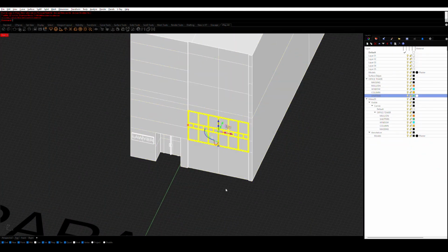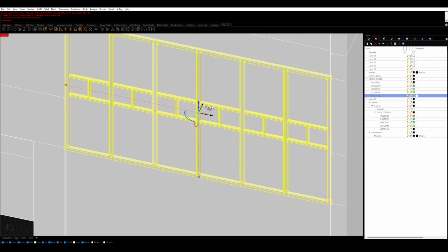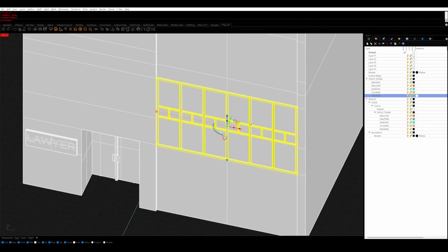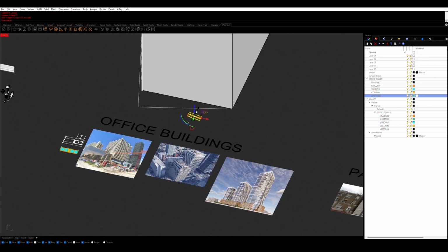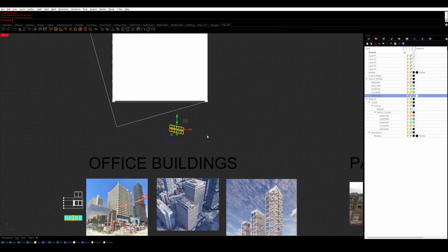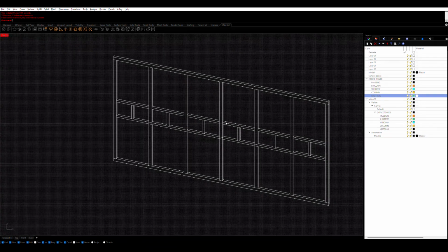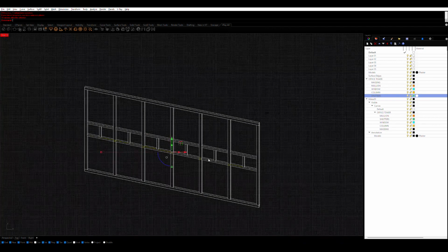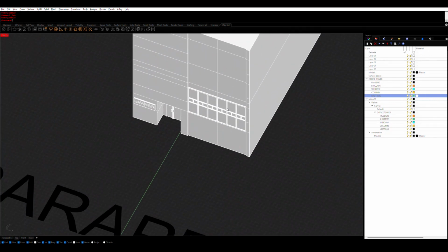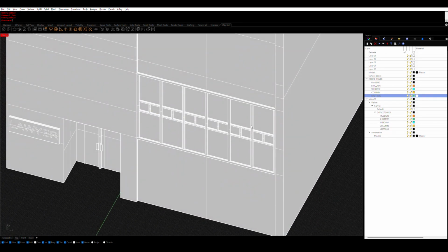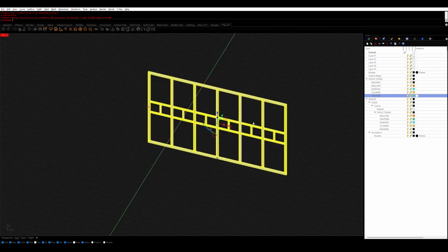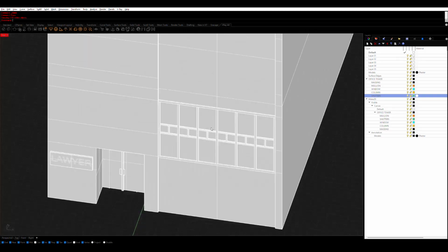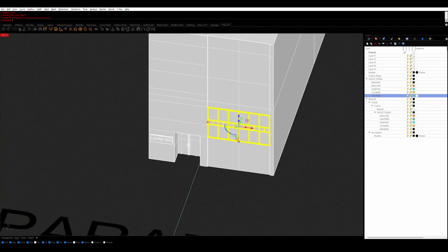Okay, that looks good. So we'll just select all of that, deselect all of that, and let's just group it together. Let's just make sure that it makes 2D properly. We did a lot of Boolean work, and we're not sure if anything is intersecting. So it seems pretty okay. I think these are just our polylines that we have. But that looks good. So from here, we can isolate this, select our curves, delete them, show the rest of the building.